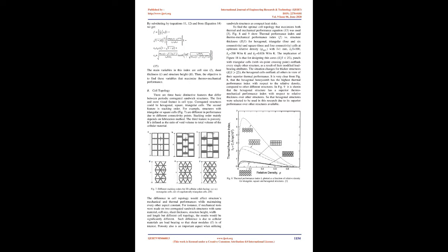Fig 4 shows the bending deformation will occur if a cell is compressed in plane. This will cause a linear elastic type of deformation. Due to this, a reduced in-plane stiffnesses and strength are likely to occur. Fig 4. Hexagonal cell, A. Undeformed, B. Upon in-plane compression initially deforms by bending.